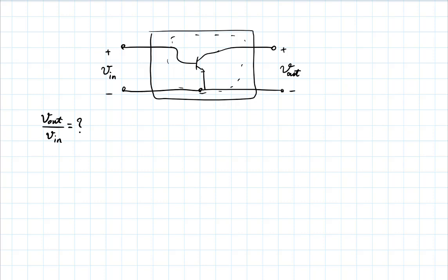But even before you can find this, what is it that you need to understand about the circuit before you can give me numbers? You have to first be able to, with some analysis, establish whether the transistor, for instance, is in saturation or active mode, right? Because if it's in saturation, it behaves in a very different way. The ratio of the collector to the base current is not that large anymore, and all the rest of it.